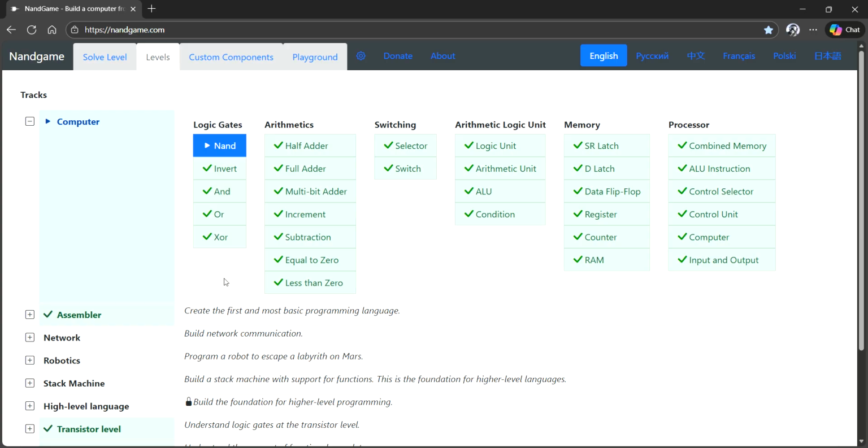The most important gates, the logical parts, are AND, OR, and NOT. AND, OR, and invert. These three can be derived from the NAND gate, and these three gates with different combinations will be able to handle any logical problem which is thrown at the computer.